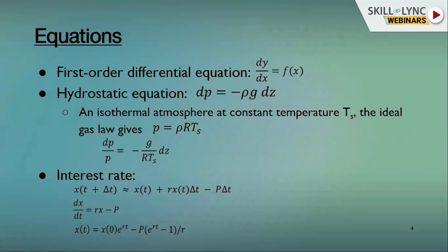Okay, so here if you see the differential form, let me use the pen. Here is the differential equation, dp equals minus rho g dz, where p is the pressure, g is the acceleration due to gravity, rho is the density of the fluid, and z is the head, meaning where my plane is.